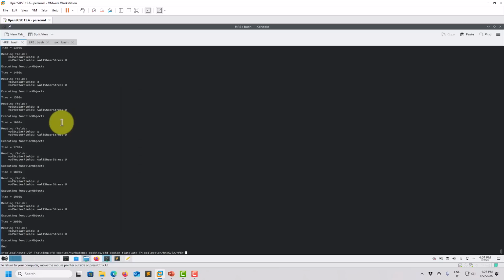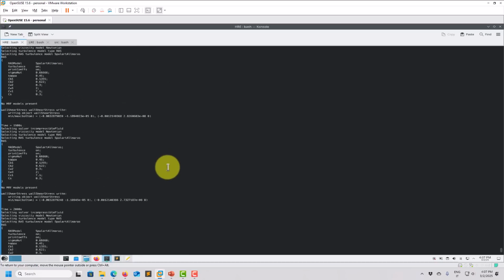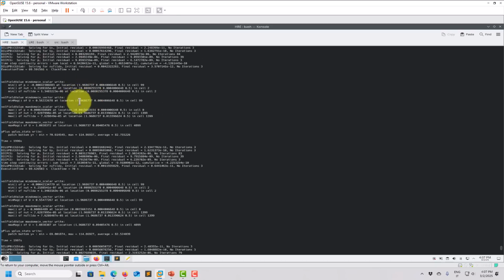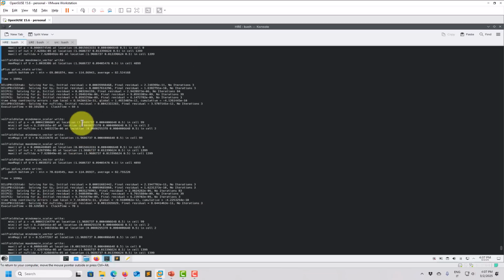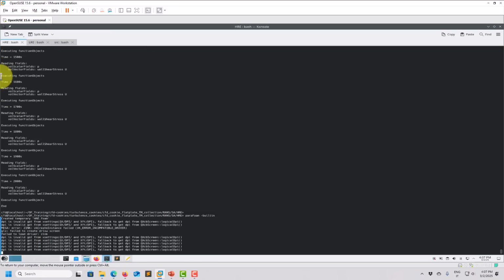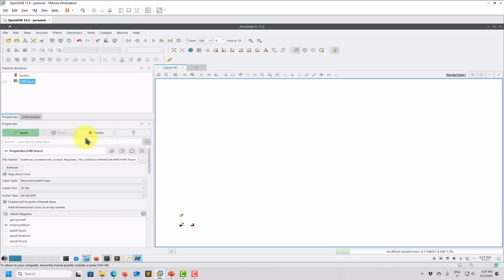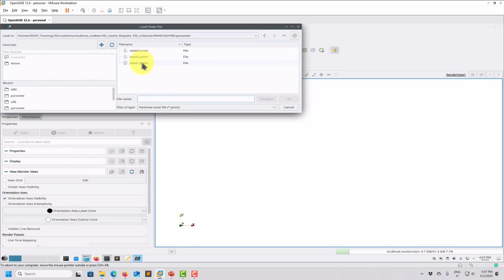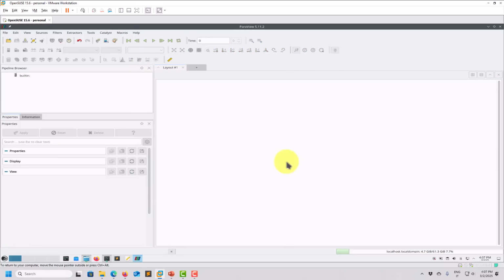But at this point, look at that, we have a solution, okay? And when the case was running, everything looked okay. So no nu tilde, nothing strange, your quantities, your y plus, okay? So you have your values there. And at this point, let's do the traditional post-processing. So we have the 3 states in ParaView, and let's look at all of them. So ParaView, state 1, okay.